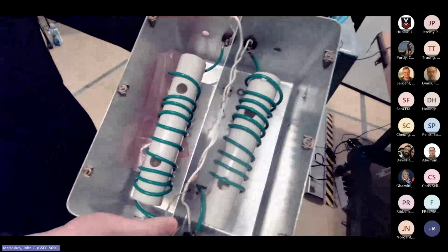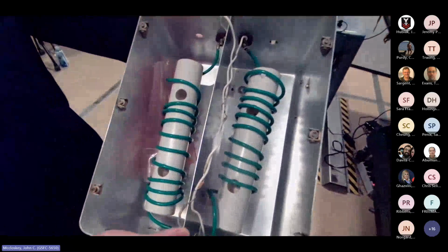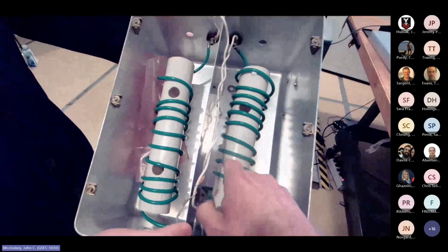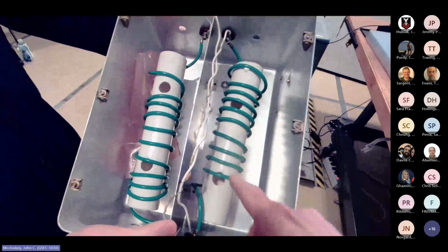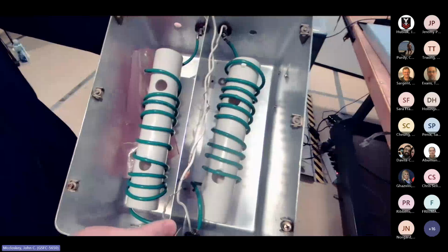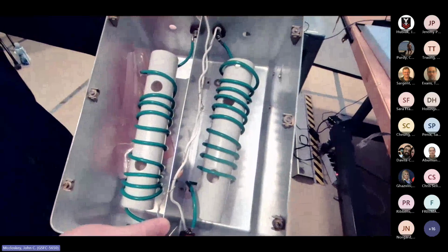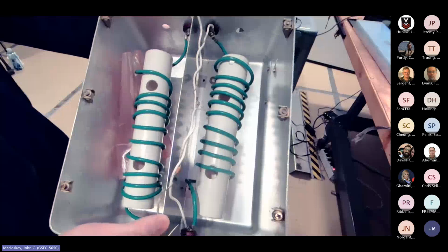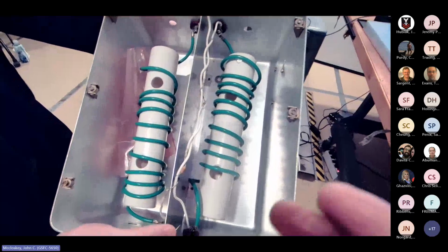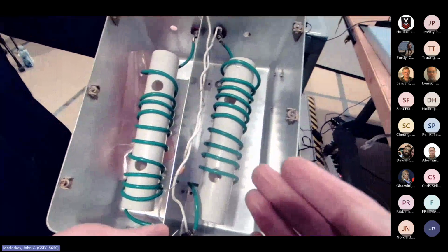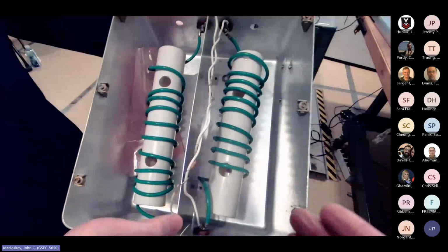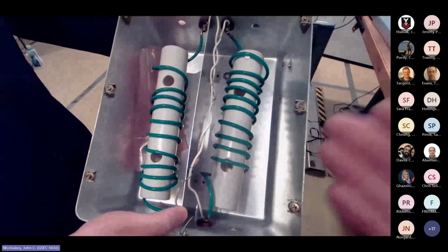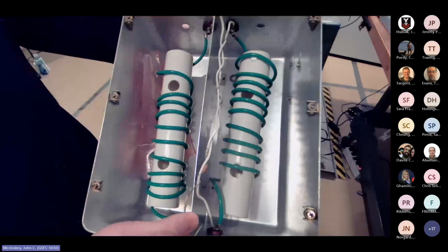Capacitance. Walt and somebody online get the tie for first prize. Yeah, there's capacitance here. Parasitic capacitance between the windings really wreaks havoc with your ability to get the desired impedance at higher frequencies. And at the end of the summer, when Annabelle had to go back to school, we got this. I don't recall, but I think we got this working up to maybe 30 megahertz or so.